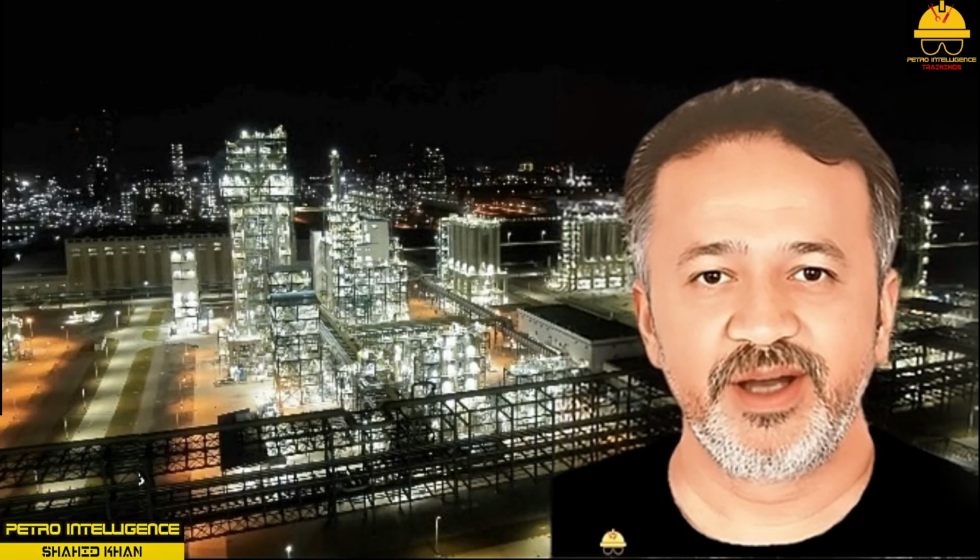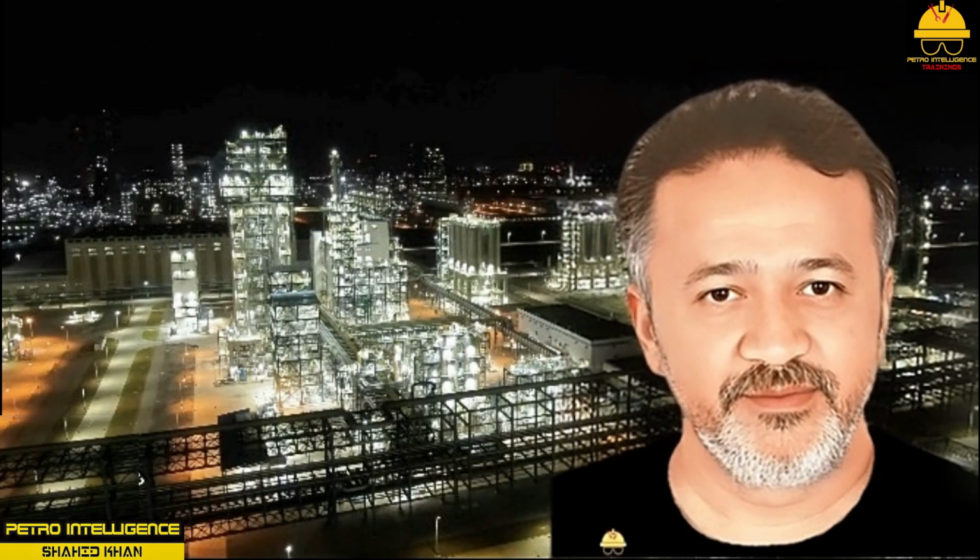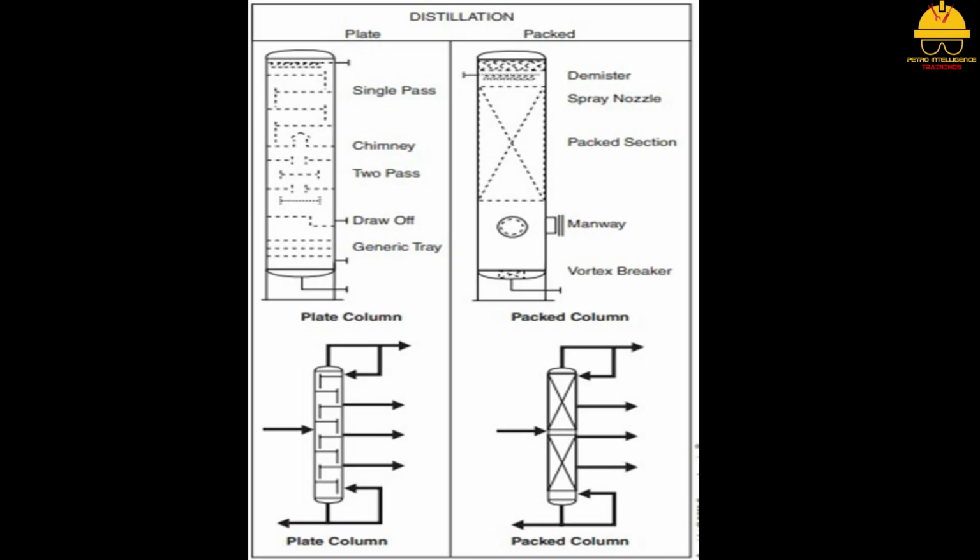Distillation columns come in two basic designs, plate and packed. Flow arrangements vary from process to process. The symbols allow the technician to identify primary and secondary flow paths. The two standard symbols for distillation columns can be found in this picture. Distillation is a process designed to separate the various components in a mixture by boiling point. A distillation column is the central component of a much larger system. This system typically includes all of the equipment symbols found in this video.